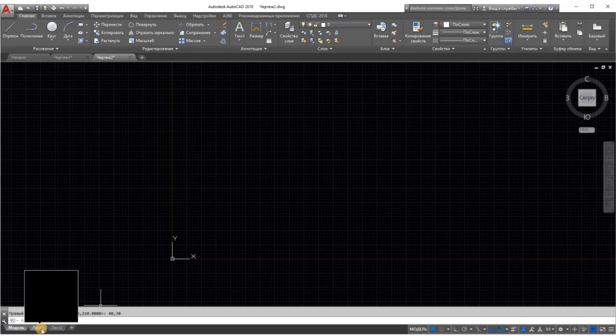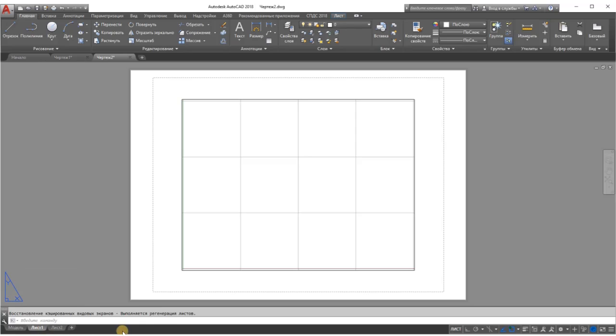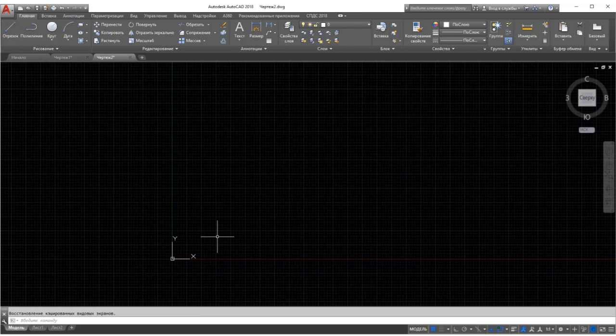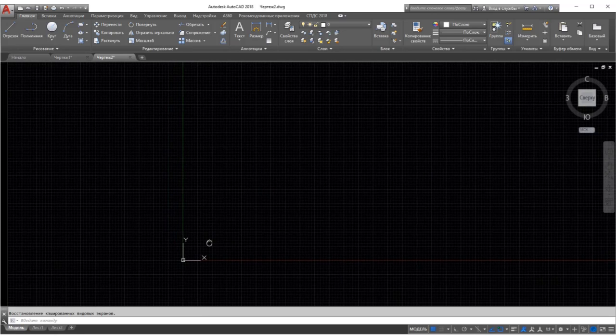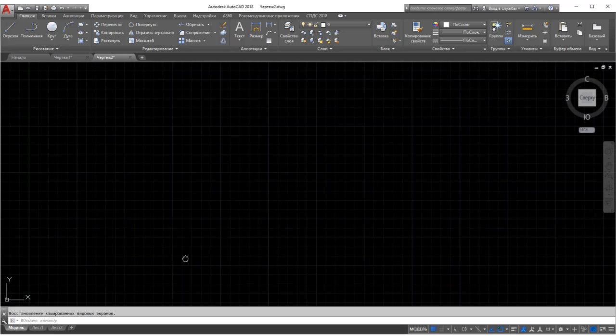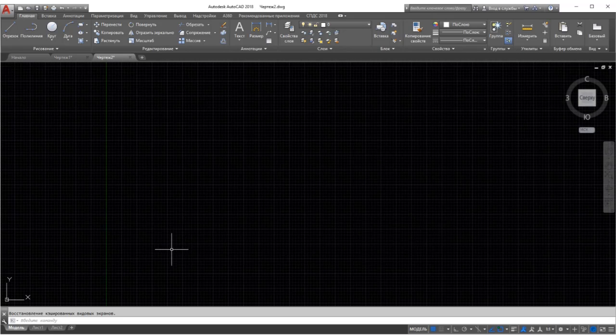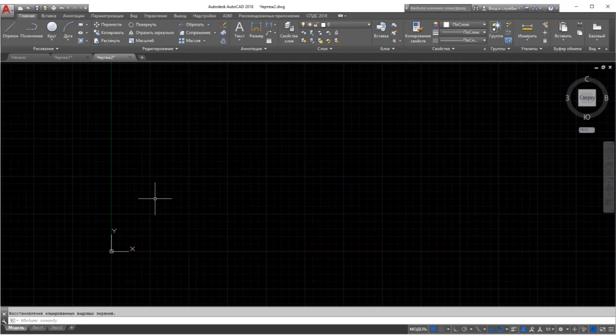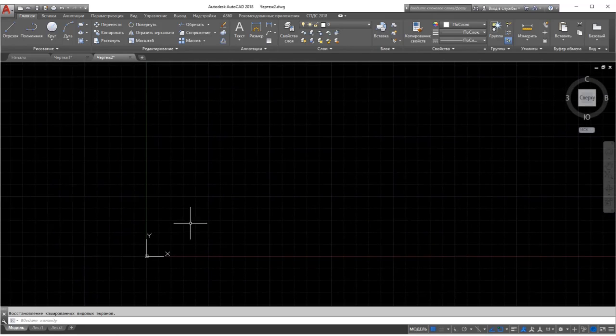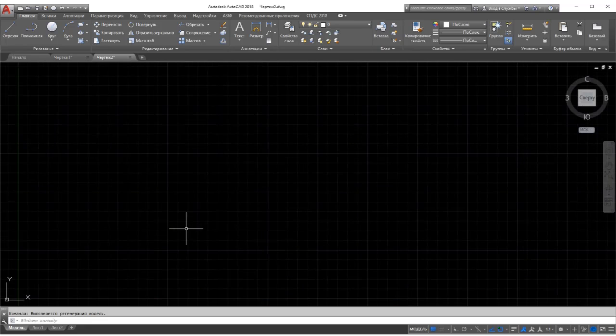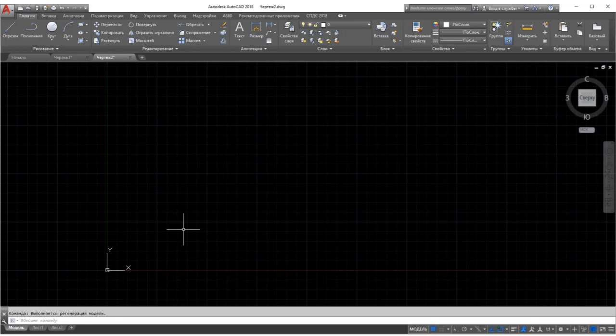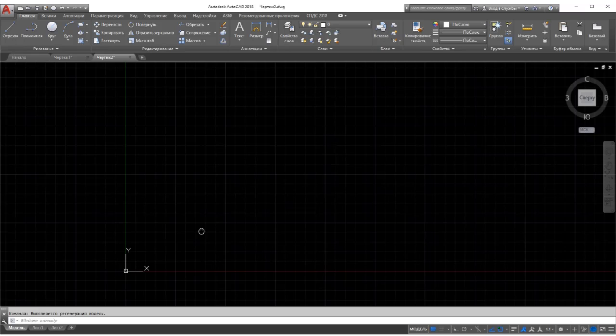To check the area size for yourself, move the crosshair cursor to the upper right corner of the drawing area and observe the value in the coordinate readout in the lower left corner. The coordinate readout won't show exactly 12,9 inches or 40,30 centimeters for metric, because the proportions of your drawing area aren't likely to be exactly 12 by 9 or 40 by 30. AutoCAD does try to optimize the display for the drawing area when you choose the All option of the Zoom command.